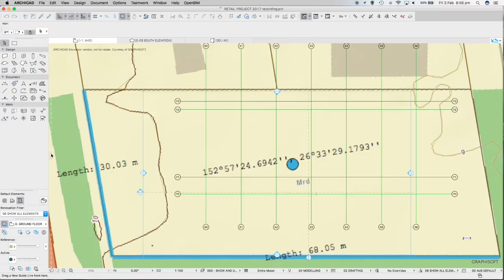So just using guidelines off to the side here, drop one on that grid, and then grab the orange dot and back 1500. And same from here, from Y3. We'll go up 1500, and so on and so forth on the other sides as well.